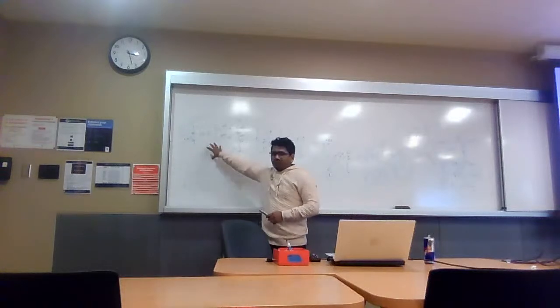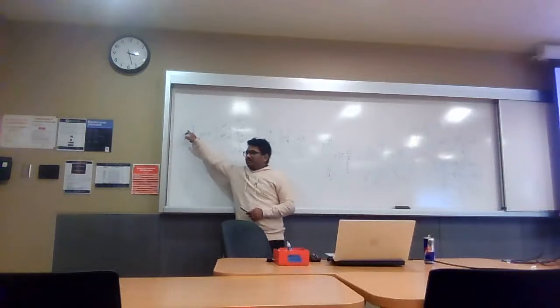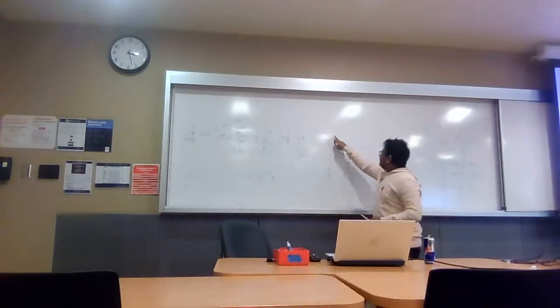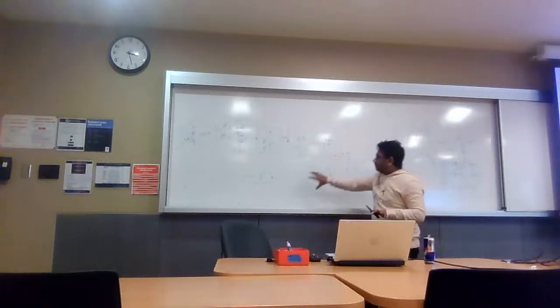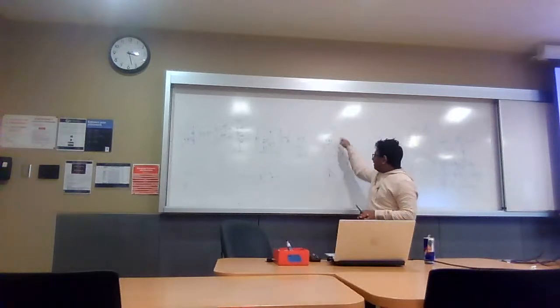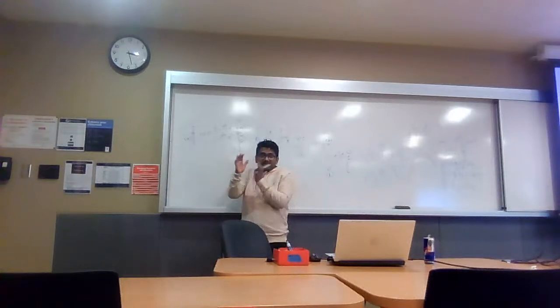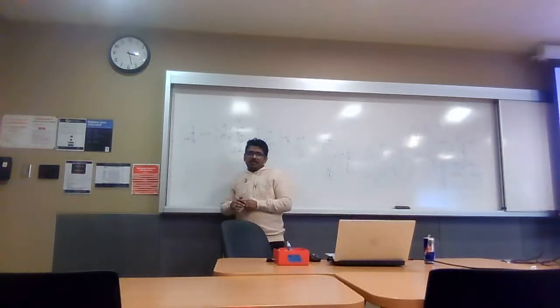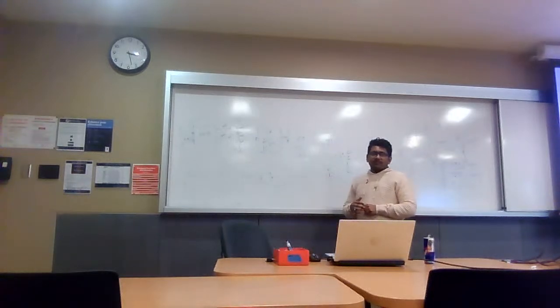This is my phase and frequency detector. Let's say the reference is 100 megahertz and we are expecting 1000 megahertz at the output. So we have to design this divider so that after dividing, we also get 100 megahertz here. Then it can compare whether it changed or not. Okay, so let's say at the output it was 800 megahertz instead of 1000. Does that mean the design for the divider changed?